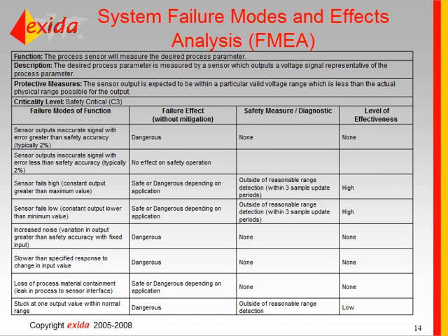There's also requirements for a probability of failure on demand. So what is the overall probability that the product's going to fail when it's needed the most? In other words, when the safety demand occurs, when it's needed to perform its function, when the gas level is high or the temperature is high or when an accident's about to happen and these systems are relied on. So these things will need to be met.